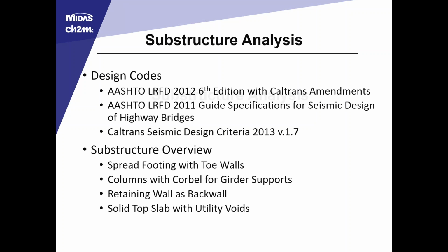So moving into the substructure analysis, again, the design code was AASHTO 2012, also using the AASHTO LRFD 2011 guide specification and Caltrans seismic design criteria version 1.7.